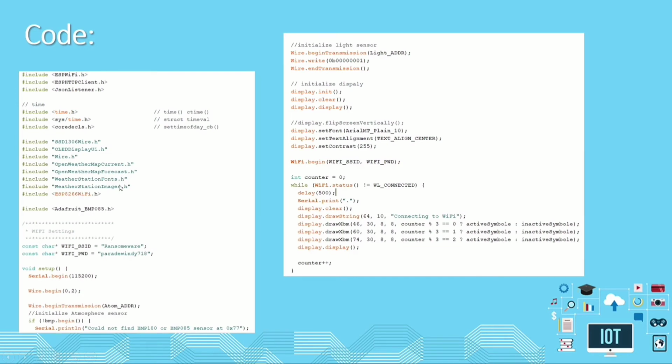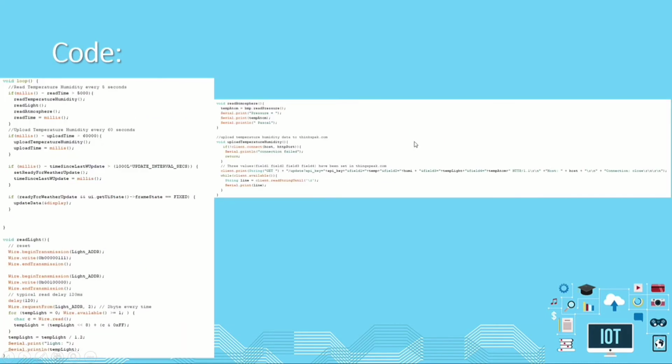These are the Wi-Fi credentials required. The NodeMCU is going to use this Wi-Fi to get connected, and then I have written the code which will initialize the wiring. First, it will check if there is any error, and if there is no error, then this part is for the OLED display. It will set up the OLED display for printing, and it will show that it is connecting to the Wi-Fi, and if it's connected, it will display the done output.